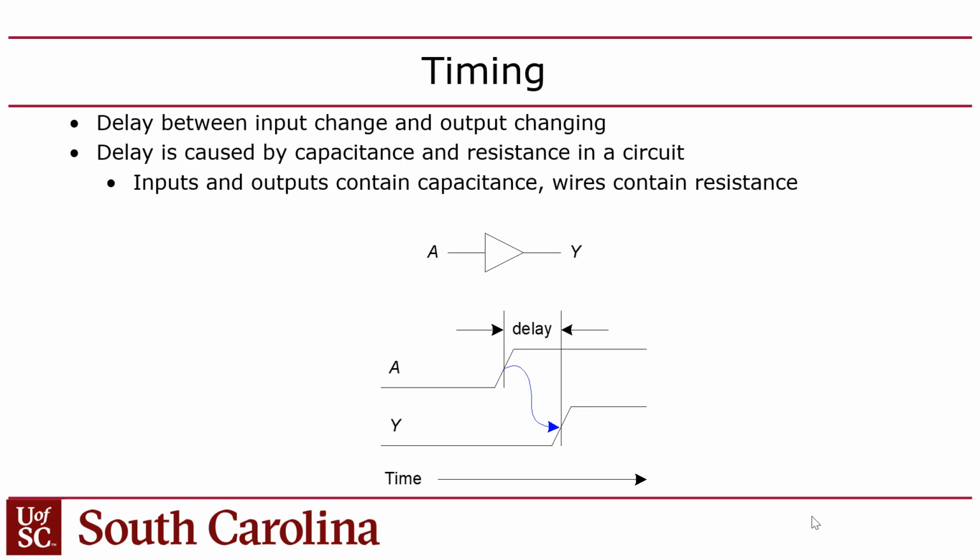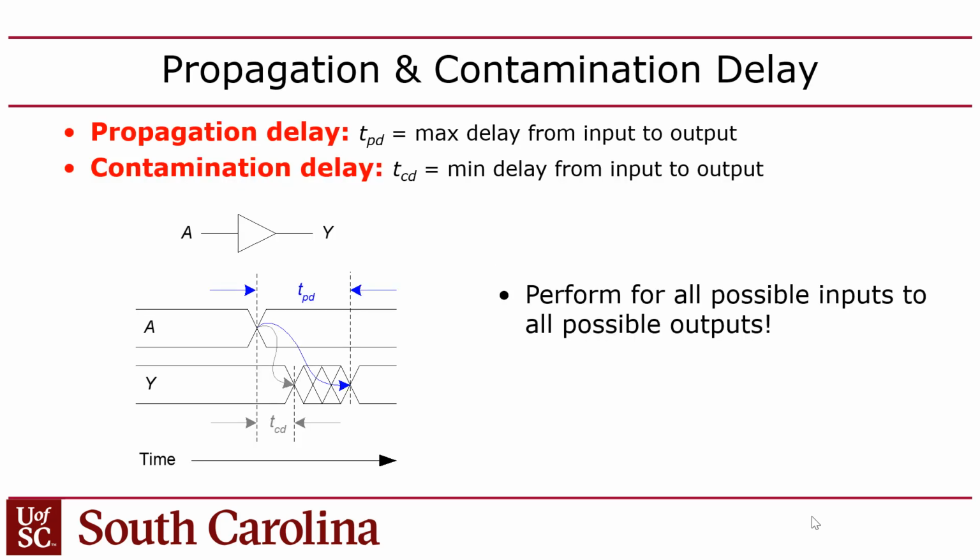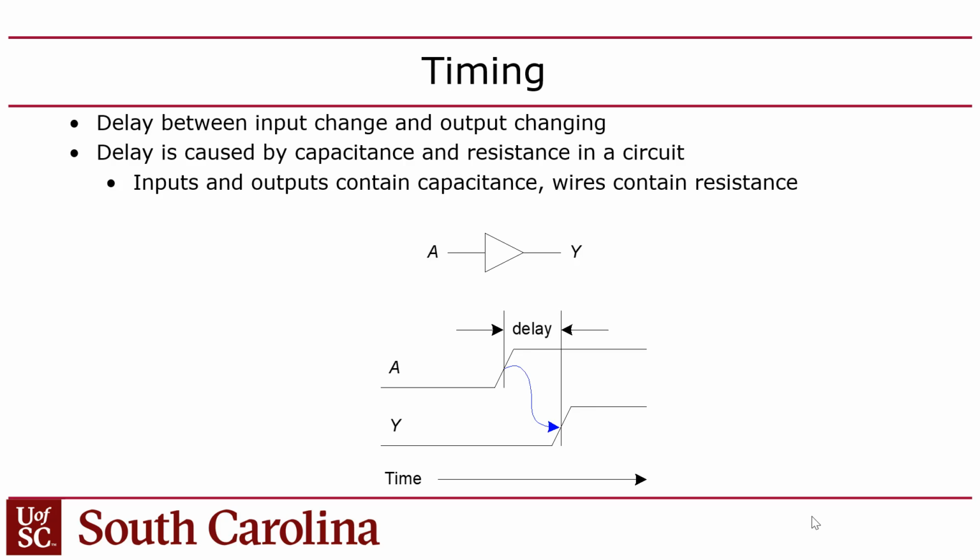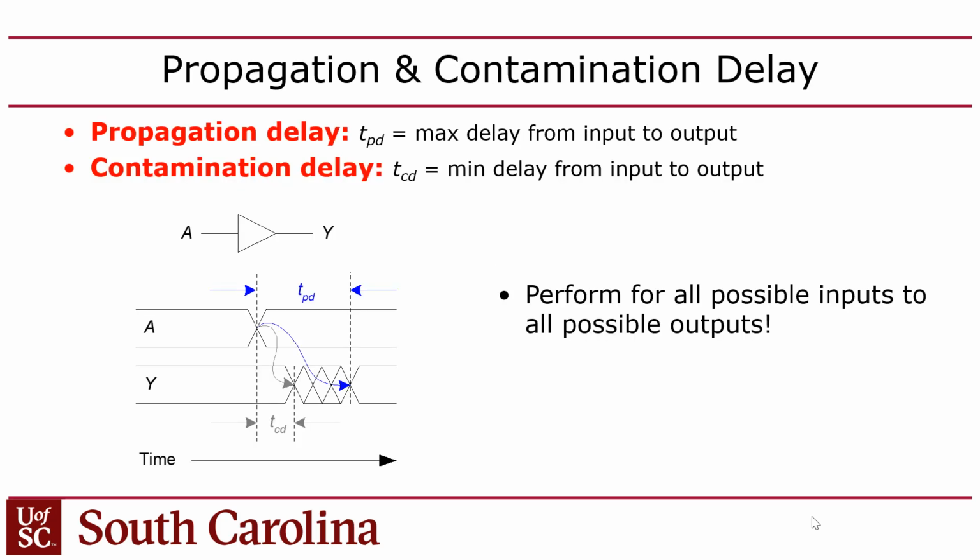Seems strange, but it works out. So that's called the RC delay. So the resistance is on the order of single-digit ohms, right? But the capacitance is usually in picofarads, right? So when you multiply those, you get picoseconds. That's the kind of delay that you get through a gate like this.